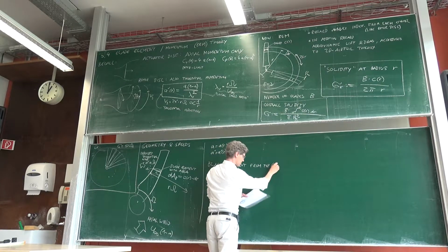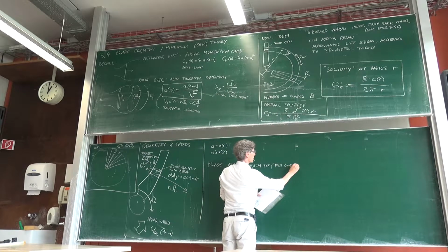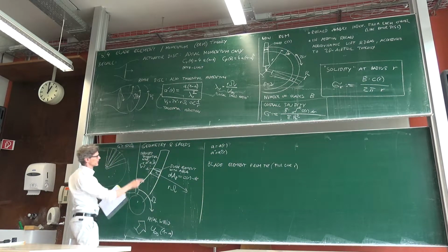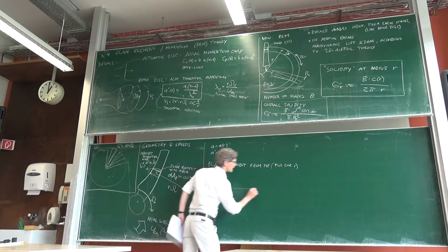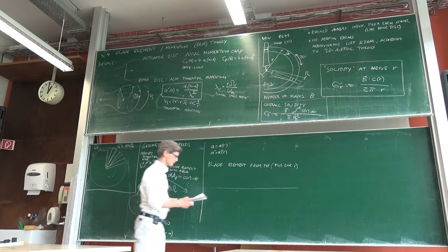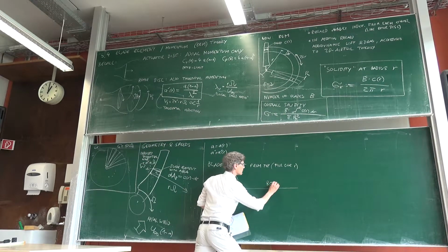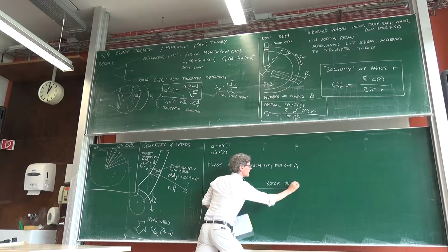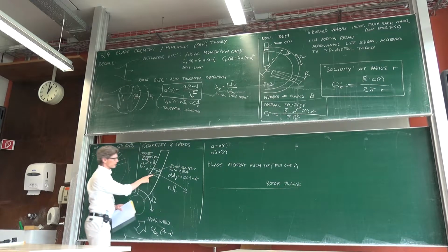And a blade should also be at the top. And it's of course for one r. So I assume that the r is now fixed. I mean, there is twist and so on in this blade, but I look just at this one element. And so here I would first draw a line that I call the rotor plane. That's the plane in which this blade element will move.